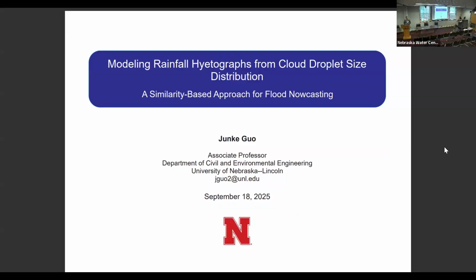Previously, the rainfall distribution was based on empirical previous data. When we design hydraulic structures or watershed designs, we build extremes based on previous data, or if we try to understand a watershed process, we have rainfall and surface flow, and we try to build the empirical relationship.